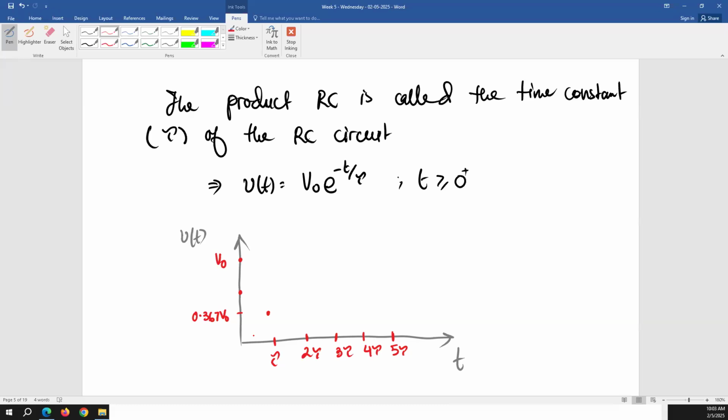If you see me in any class in the future, advanced classes, I teach advanced classes, and if I ask you what the time constant is, because we're going to use it in multiple classes, make sure you give me this definition, because I know that I told you this definition. So write it down, remember it. The time it is going to take for the response to drop down to 36.7% of the initial response value is the time constant of the circuit.